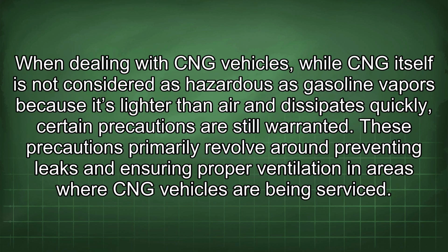When dealing with CNG vehicles, while CNG itself is not considered as hazardous as gasoline vapors because it's lighter than air and dissipates quickly, certain precautions are still warranted. These precautions primarily revolve around preventing leaks and ensuring proper ventilation in areas where CNG vehicles are being serviced.